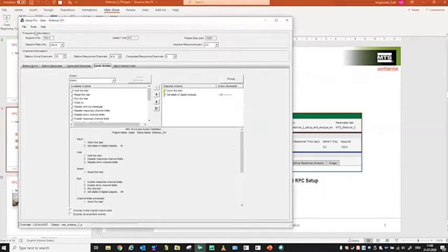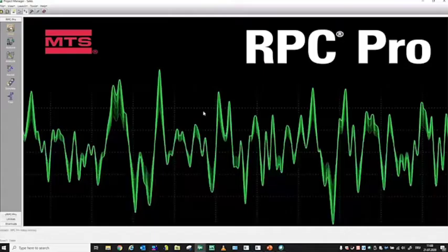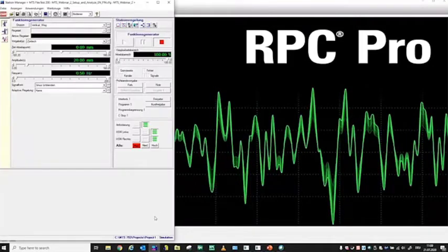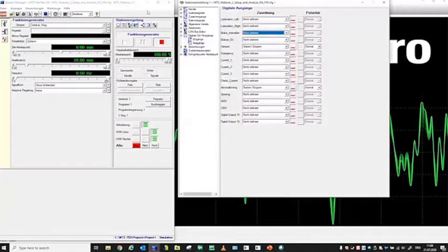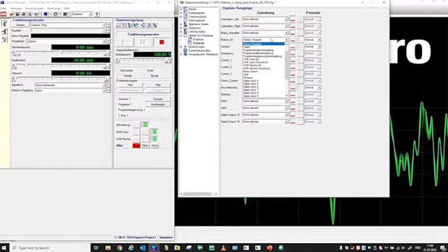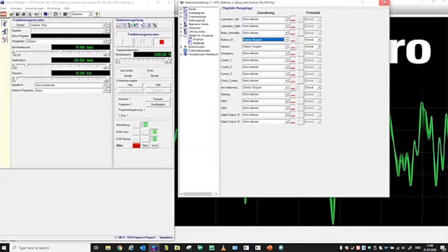So what happens now if I save that setup and say, okay, I'm going to disconnect from the station. So now I'm going to clamp the brakes manually because I need to do some investigations on my rig, or I want to trigger them manually. So I go into the station manager, go into the digital output section and say here, brakes on. I say, okay, it should start or stop, or I just directly hit it to enable it, whatever I define here. I make a change in the digital outputs. And this causes a lot of troubles in RPC Pro.